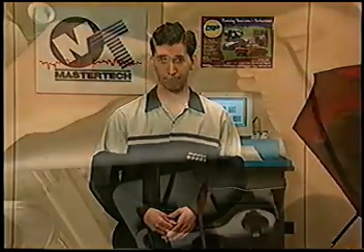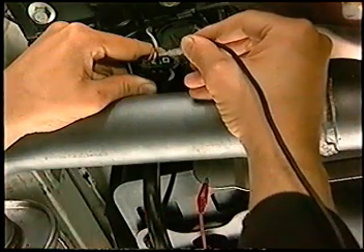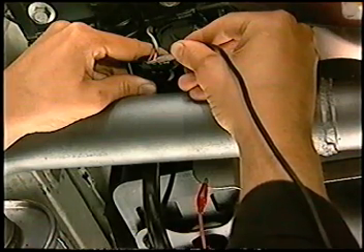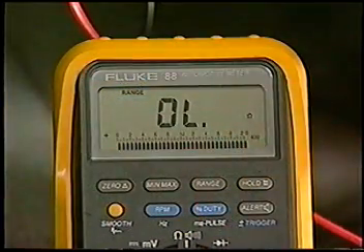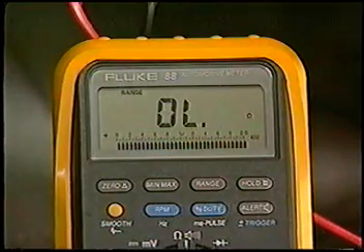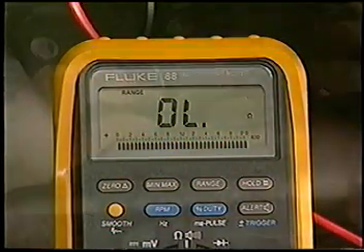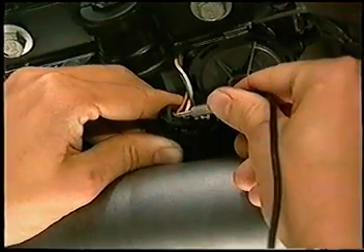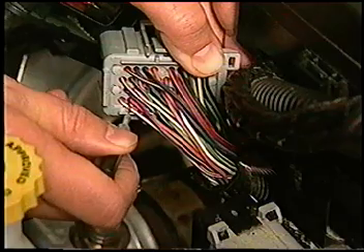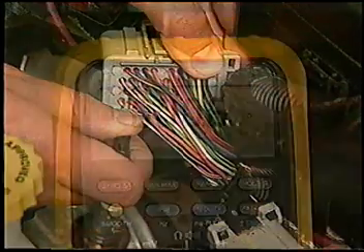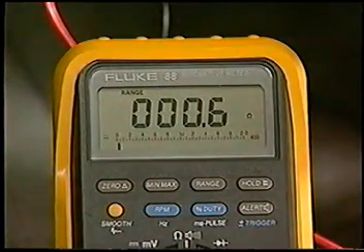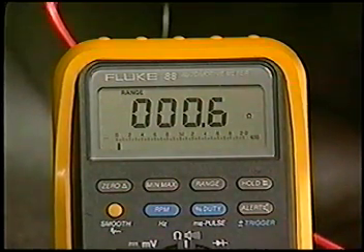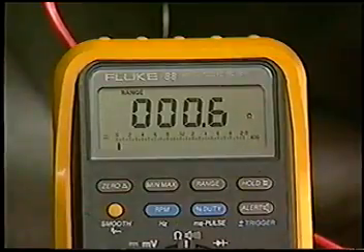At this point, I suspected the leak detection pump was good and that the cause had to be somewhere in the switch sense circuit. So I measured the resistance of the LDP switch sense circuit in the LDP harness connector to ground. Resistance of above 5 ohms told me that the circuit was not shorted to ground. I then measured resistance of the LDP switch sense circuit between the LDP harness connector and the PCM harness connector. Resistance should have been below 5 ohms. However, it wasn't. So I knew that I would need to check the LDP switch sense circuit for an open.